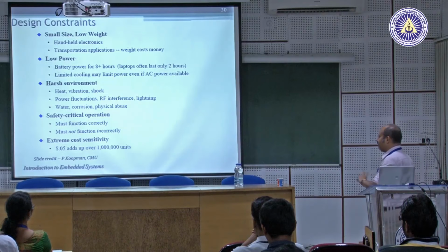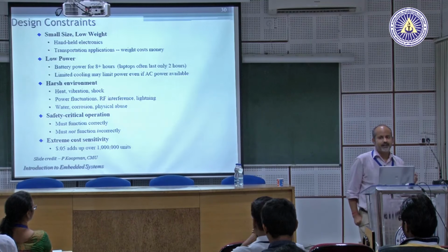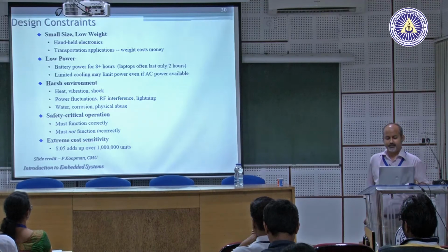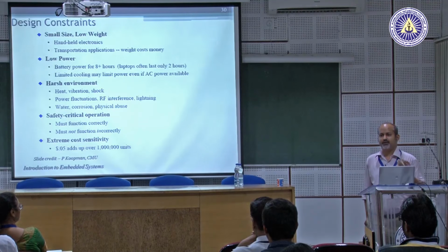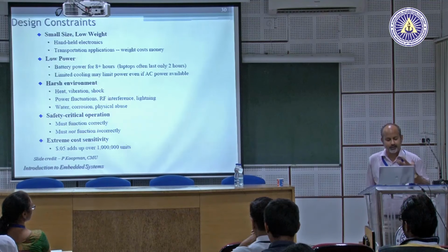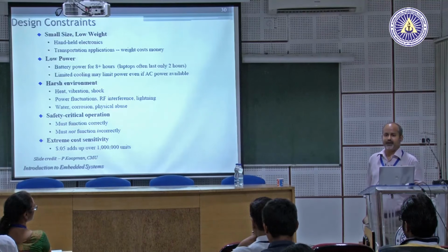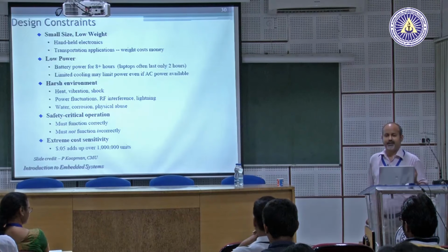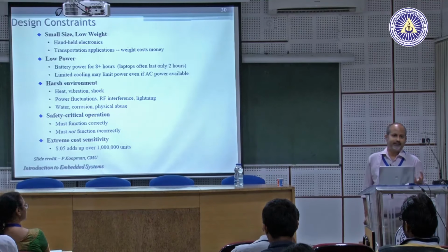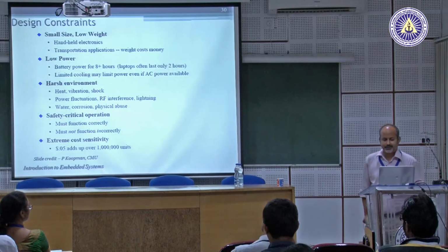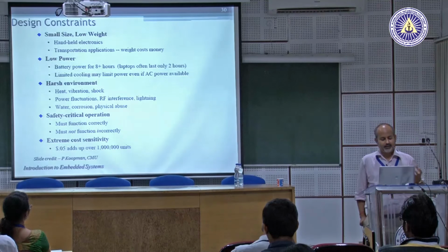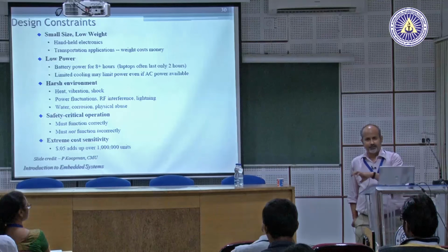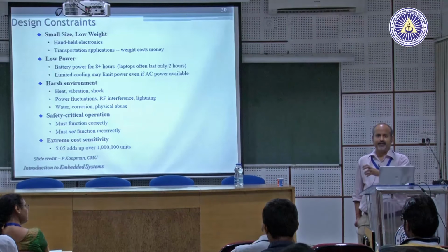safety criticality. Not all embedded systems are safety critical, but a flight guidance system, or the system that goes into your car for anti-lock brake or for cruise control, must be done in such a way that it is correct with a 99.999% guarantee, because you cannot have these kinds of systems malfunction, because human lives and property are in danger. These are called safety critical systems. If your embedded system is safety critical, then you have to worry about making sure that it is up to that standard of safety criticality.